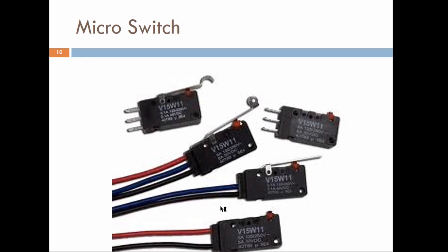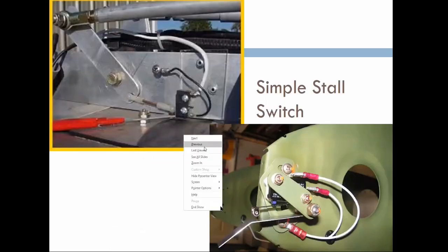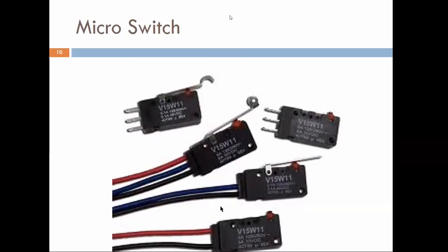The switch part is only right here. So again, it's a very tiny micro switch, but using an arm or a lever, we can activate it, which makes it nice that we can mount it close to moving parts so that we can get it to open and close for flaps. So fully extended, fully retracted, and it will stop the travel.